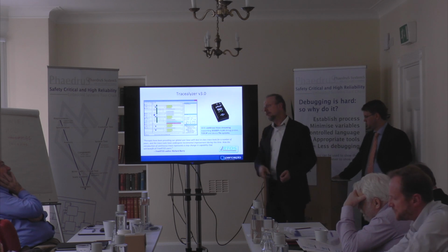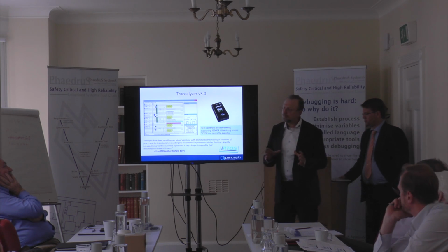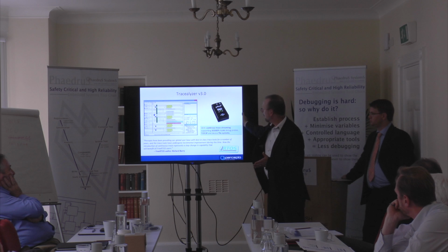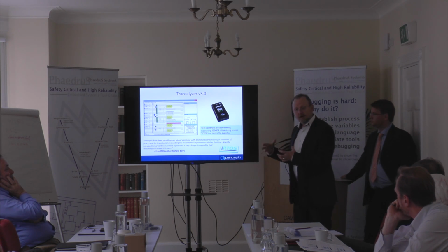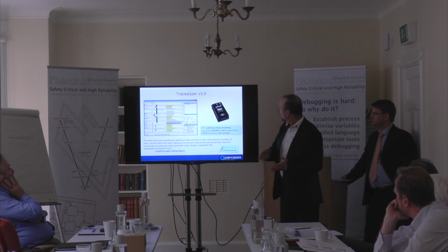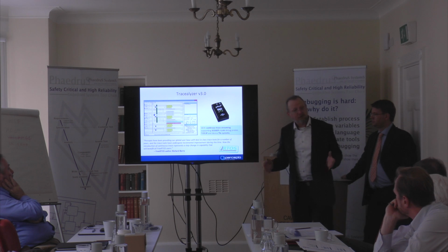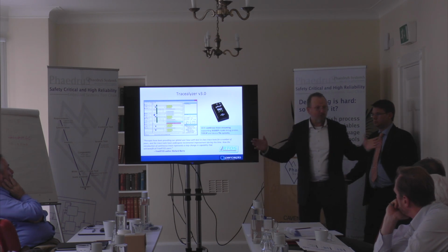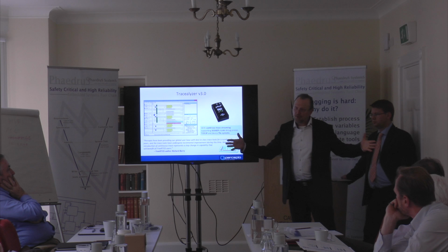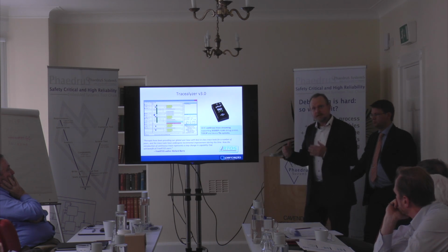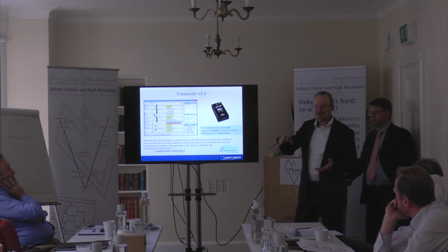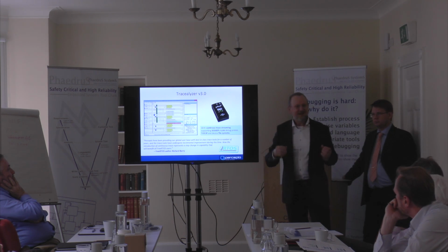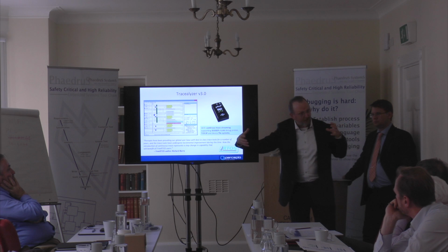What we're talking about now is streaming trace, and we're going to stream that over J-Link or TCP or other channels. So we're streaming the trace out continuously, and we're talking about very long traces, 20 minutes, arbitrarily long traces. This gives you massive amounts of trace data. So conceptually, we've got a way to look at your elephant in 3D from all kinds of angles.